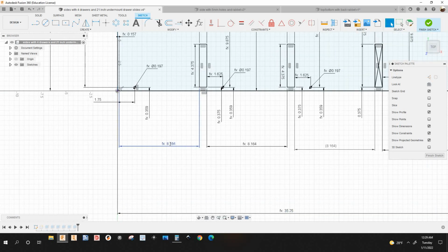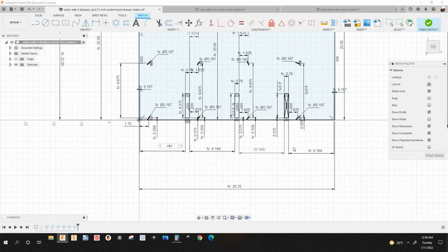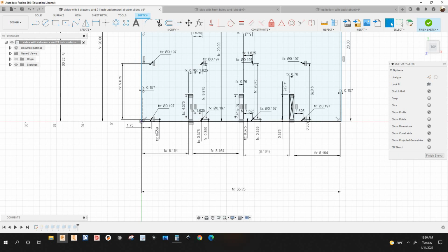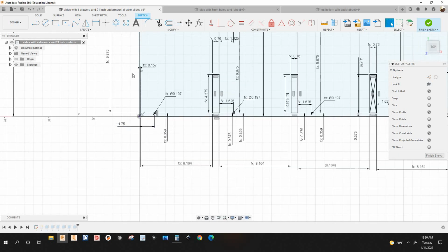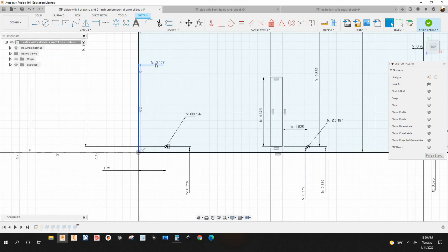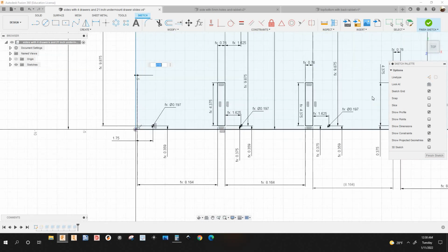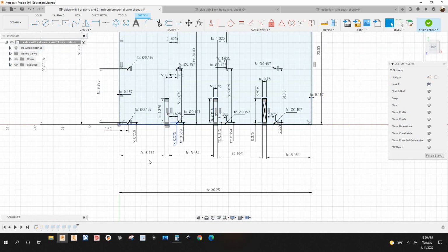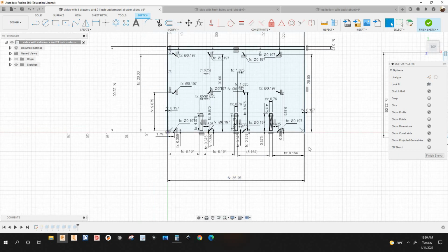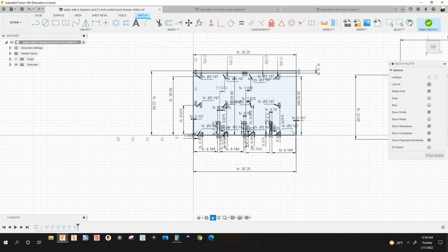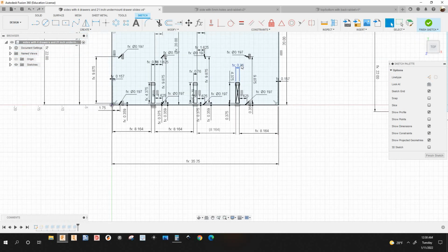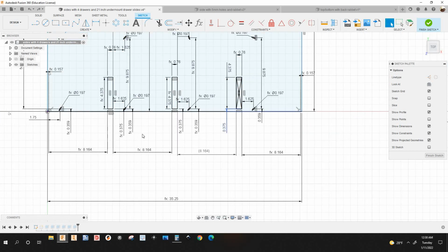Okay. I did the same thing here. But I copied this dimension from this. That's why I see D110. And I copied these dimensions as well right here. Whereas I have a second construction line right here. See that? I got D109. It's copied from this dimension right there. Okay. So see everything here. I have the thickness, which is 19.2 millimeters of the divider.